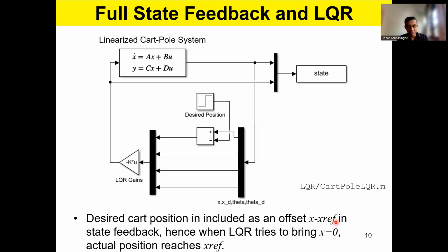So it is bang-bang control, or deadbeat control, right? You fire the engine, fire the actuator at full throttle and keep it for a certain duration. So full throttle duration, and then you turn it off. That's it. Okay. So the other phase of the deadbeat control is go to the negative maximum and keep it there for another certain period of time.